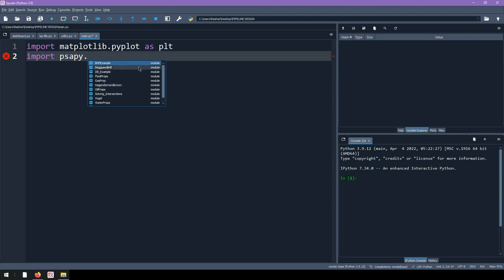If you are not familiar with these two, they used to be some of the most famous correlations. Beggs and Brill is used on almost all angles, but it's preferably used on horizontal pipe sections. Hagedorn-Brown is recommended for vertical pipelines, or for wells. For this example, we will use Beggs and Brill.